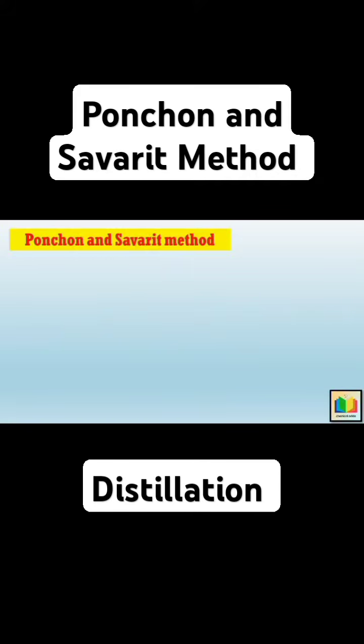Ponchon and Savarit Method. This method was developed in 1921-1922. The Ponchon and Savarit method is similar to the McCabe-Thiele method, but it involves material and energy balance equations as well as the equilibrium relation. So, both the McCabe-Thiele method and the Ponchon Savarit method are the most common methods used for the graphical analysis of distillation processes.